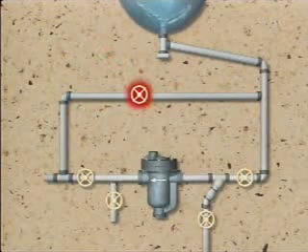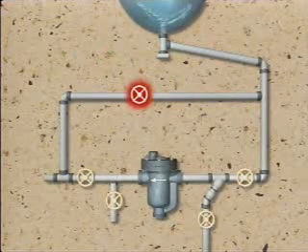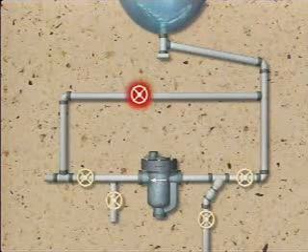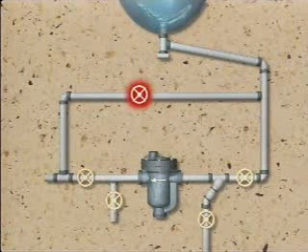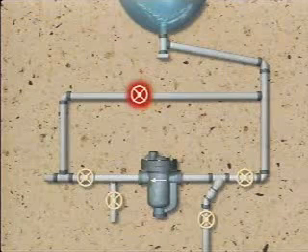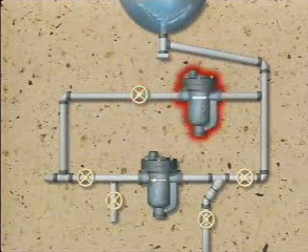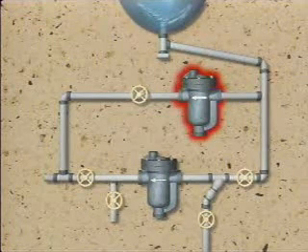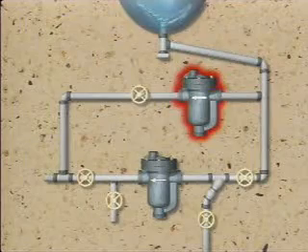The bypass valve is usually opened when there is a suspected problem with the trap. Opening the valve may be necessary to keep the facility operating, but as long as the bypass valve is left open, steam blows through the bypass and the efficiency of the steam system is reduced. Sometimes a steam trap is installed in the bypass line. Then, if the main trap fails, the bypass trap can be put into service, and the problem of blowing steam through the bypass line is eliminated.